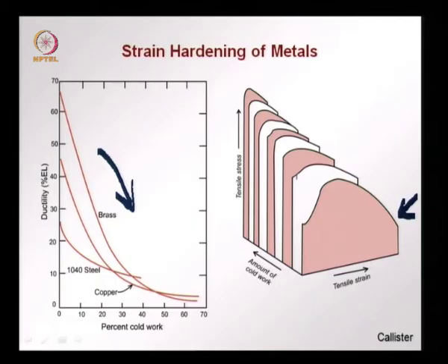However, this elongation is now less because we have used up some of the plastic deformation when we did the cold working. Now suppose I were to do this again with the original material, but I stop at a later point, I go up to here and then I unload. This new material, if I test it again, will start from here, go up here, this would be the yield point, then it would reach a peak and so on. Here I would have a large elastic regime followed by yielding, and immediately I have necking occurring and failure.